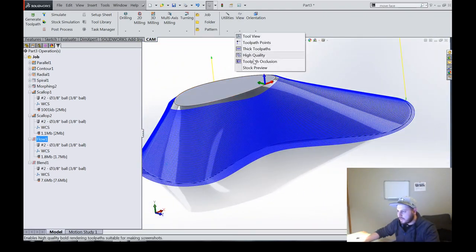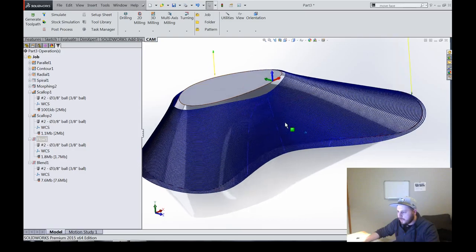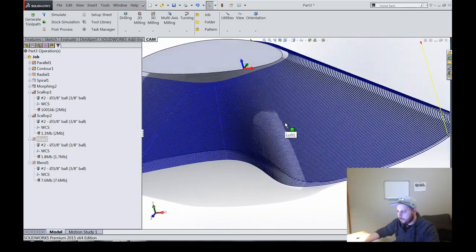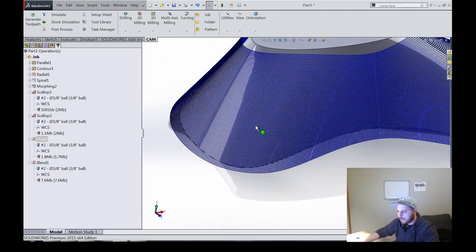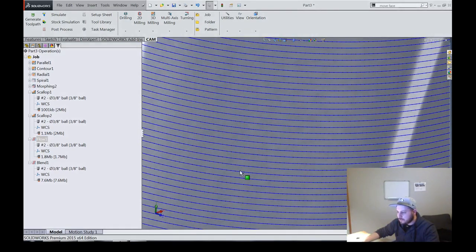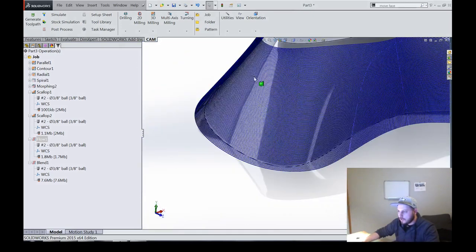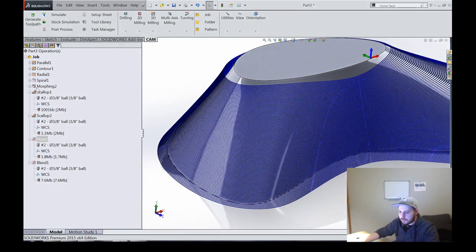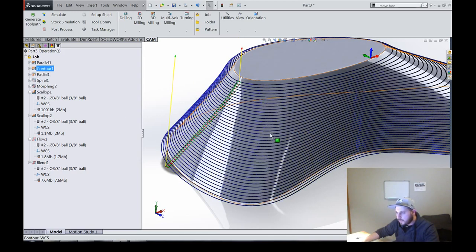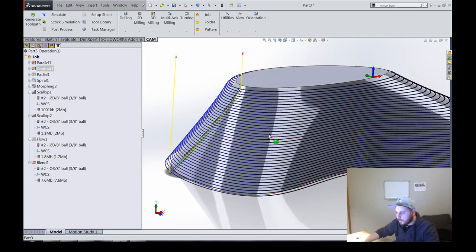I didn't get into this on the other toolpaths, but it has a tendency to have very nice tool point distribution. The breaking points of the toolpath itself have very great distribution, which is something you won't necessarily see on, say, a Scallop. You can see how much grouping there is, or on your Contour, maybe. Yeah, that one's actually not that bad.